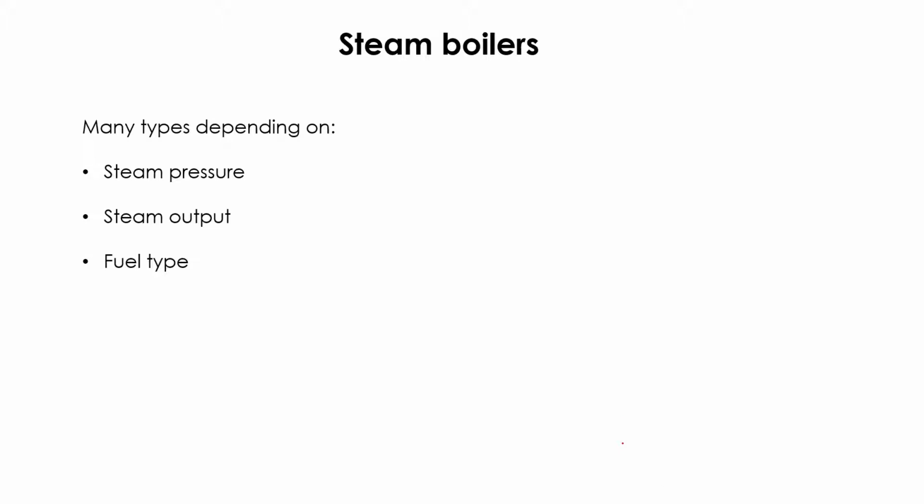There are four classifications of the pressure coming from the boiler. The first one is high pressure, which is 100 bar gauge. This is normally used for power generation. The second one is at a pressure of about 40 bar gauge. 40 bar gauge basically means 41 bar absolute. It is the normal maximum pressure for distribution.